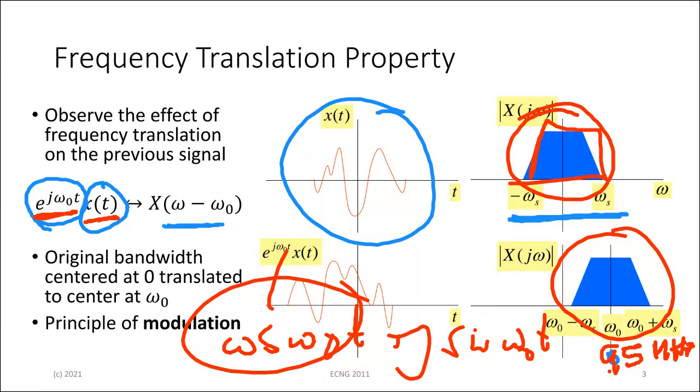So we did the spectrum of the impulse, and we saw that the unit impulse had a flat, infinitely wide spectrum. We did the spectrum of a pulse, and we saw that if we made the pulse narrow and tall, the spectrum moved from the sinc type function spectrum to a flatter and flatter spectrum. If in theory we can make a pulse very, very narrow and very, very tall, we can almost get the flat spectrum of the ideal impulse.